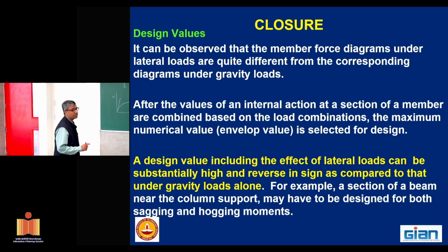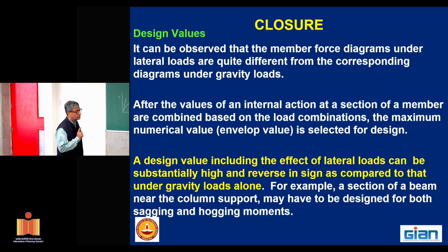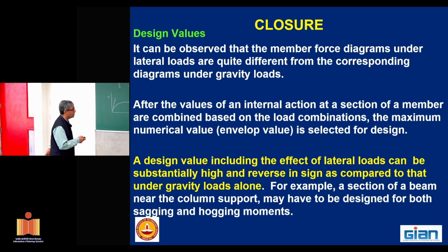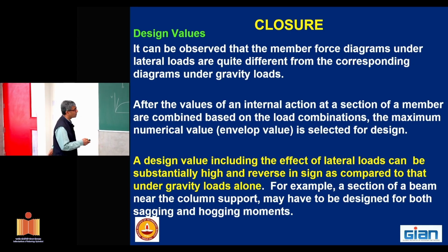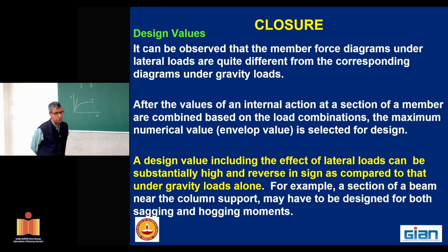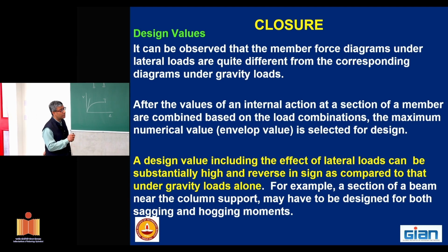Let me just read out so that it gets internalized for you. It can be observed that the member force diagrams under lateral loads are quite different from the corresponding diagrams under gravity loads. I started this lecture by saying that sometimes people assume that your factors of safety will take care of the lateral forces. No, it will not, because the force diagram is different.